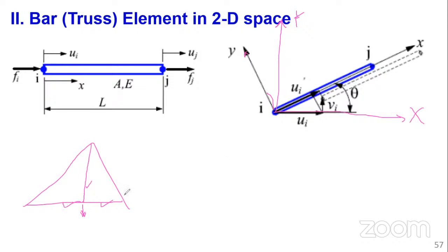So we are saying the quantity, deformation U, we want to transform it to see overall for our truss structure, the deformation for this member in the global coordinate system, so that you can see the sum effect.